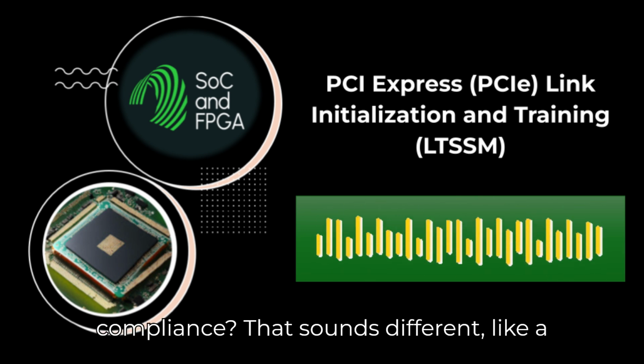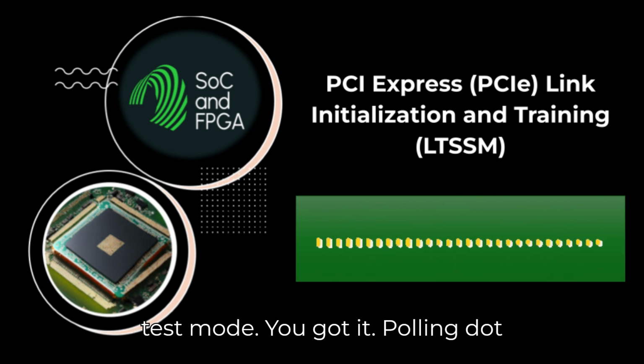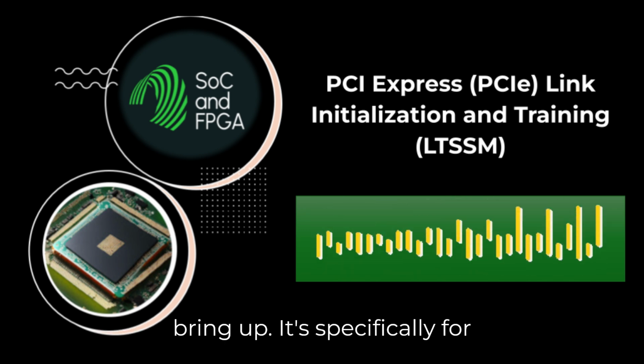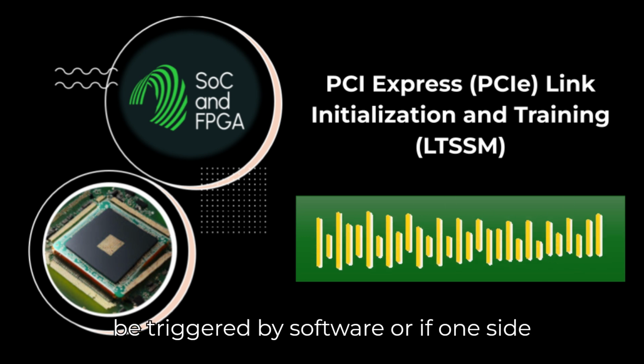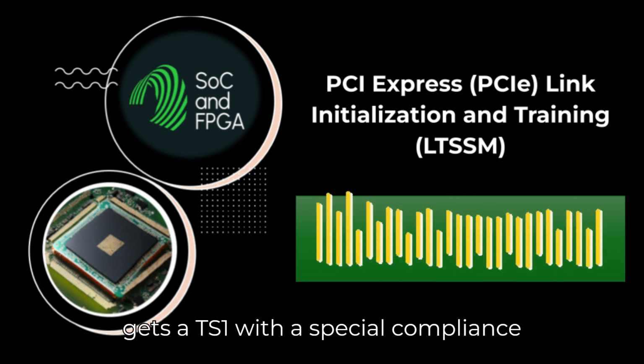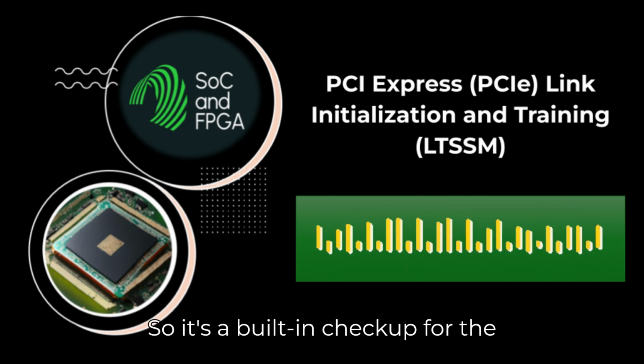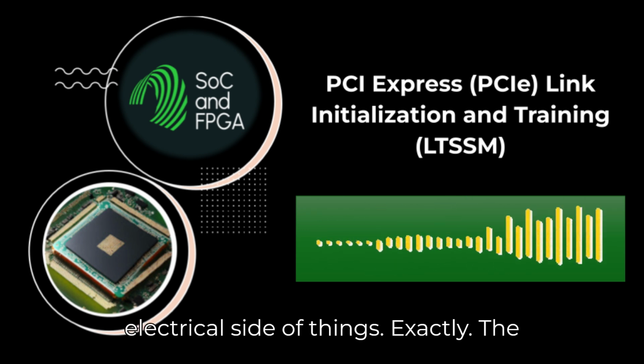And what about Polling.Compliance? That sounds different, like a test mode. You got it. Polling.Compliance is not part of the normal link bring-up. It's specifically for electrical compliance testing. It can be triggered by software, or if one side gets a TS1 with a special compliance receive bit set, or sometimes if link training just keeps failing repeatedly. So it's a built-in checkup for the electrical side of things.